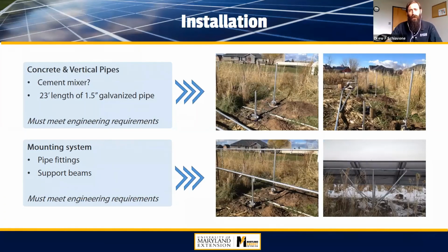Now here's a look at the structure actually being put in. This was done with bags of cement. I would recommend getting a cement mixer, renting one of those if you're doing a system. It really depends on the amount of work you want to put into it, the size of the system, and how many piers you're putting into the ground. It's going to take quite a bit of cement depending on how many you're putting in.